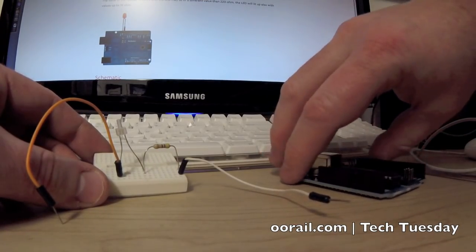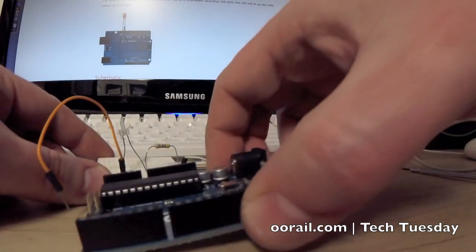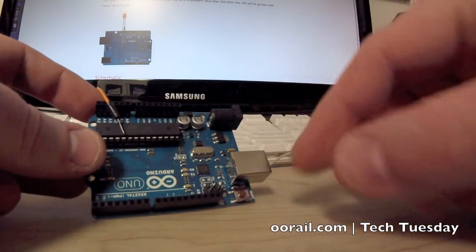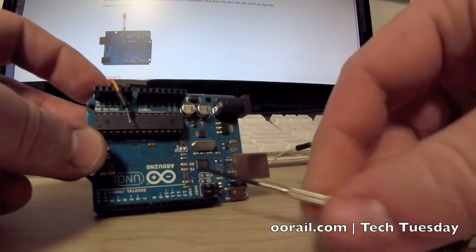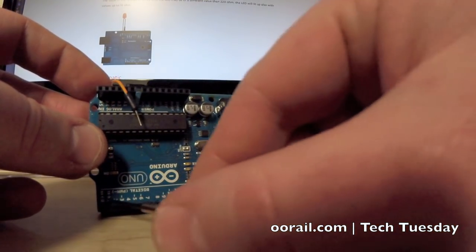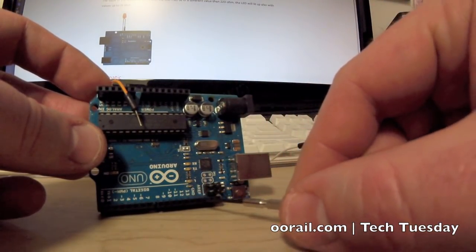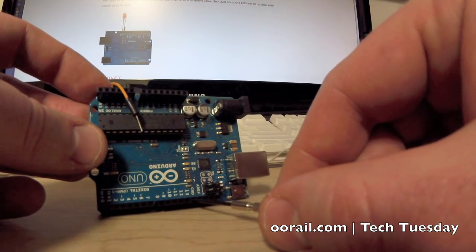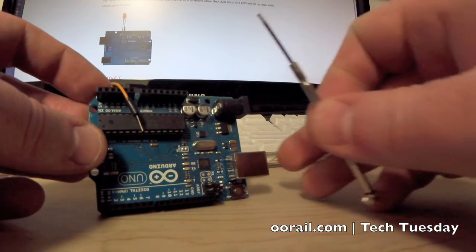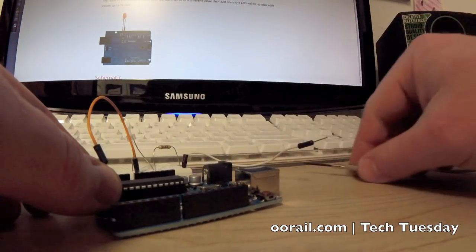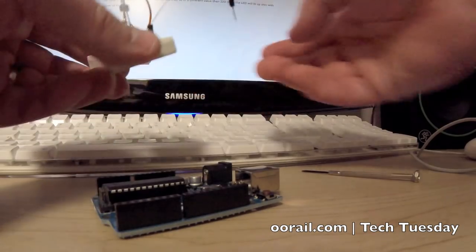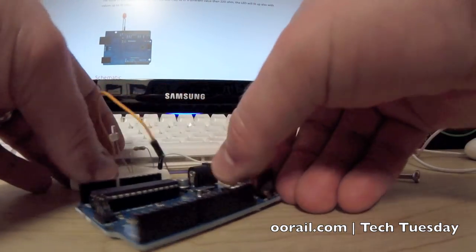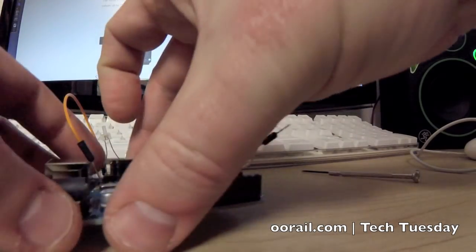So what we're going to do next is we're just going to connect the circuit to the Arduino. If you look at the Arduino itself, you can see that there are some numbers along the bottom here, and you can see GND is for ground, and it corresponds to this pin, and then this pin here is pin number 13. So I'll just do it this way, and I'll drop it in this way.